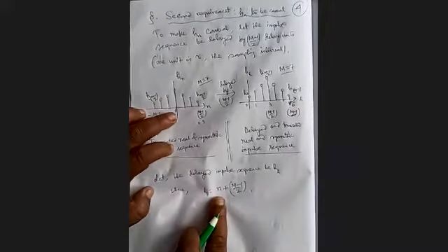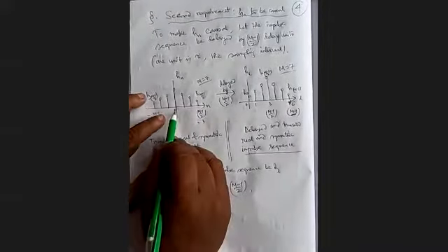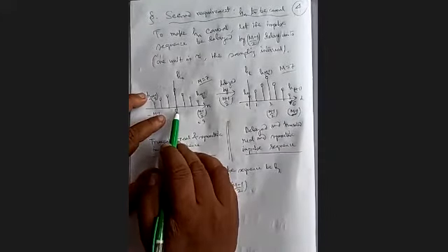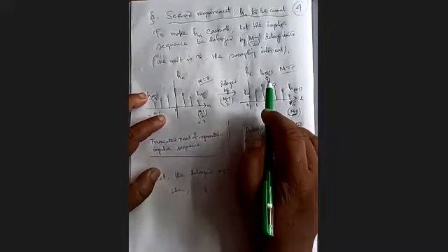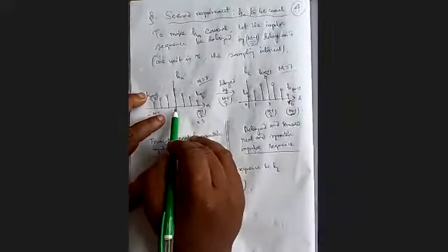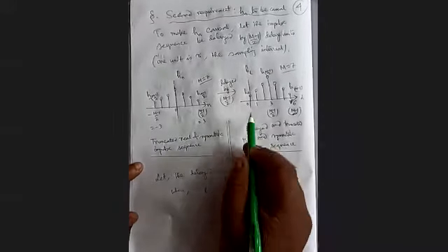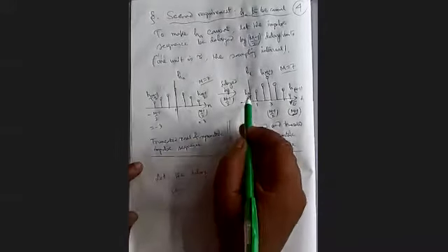Note that when n equals 0, this sample will be h of (m minus 1) by 2. When n equals (m minus 1) by 2, L will be (m minus 1) by 2 plus (m minus 1) by 2, so m minus 1. Similarly, when n equals minus (m minus 1) by 2, L will be 0. So this thing will become 0 after the delay operation.